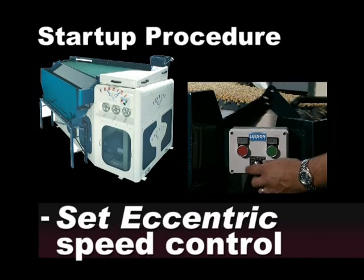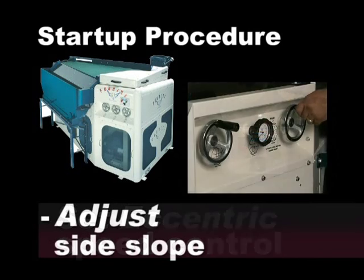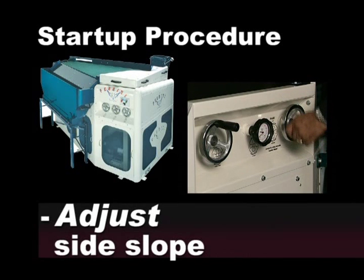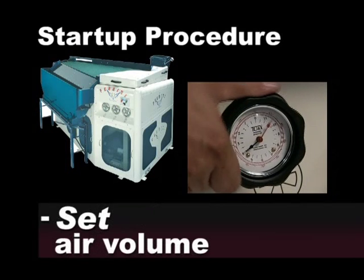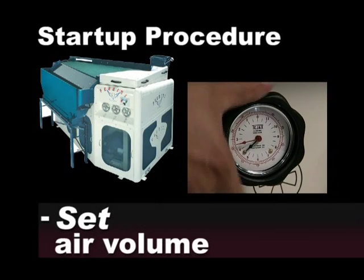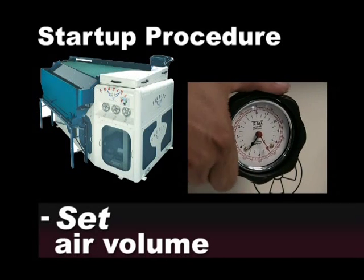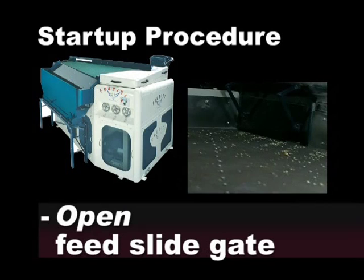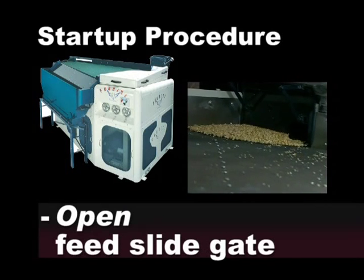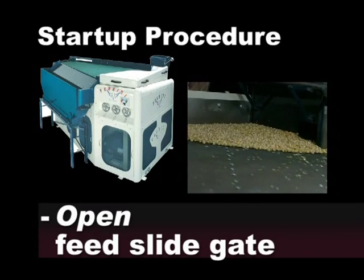Next, set the eccentric speed control to about the 50 to 60% point and then adjust the side slope. For corn, a side slope angle of 4 degrees is a good starting point. Now set the air volume to at least 50% open. Once these initial settings have been confirmed and all equipment is running, then slowly open the product slide gate that controls the feed rate of product onto the deck.